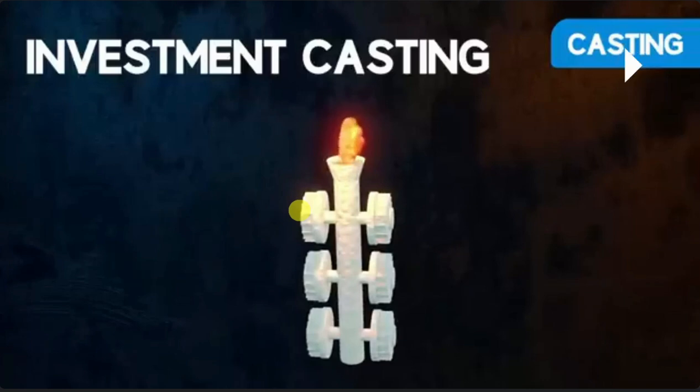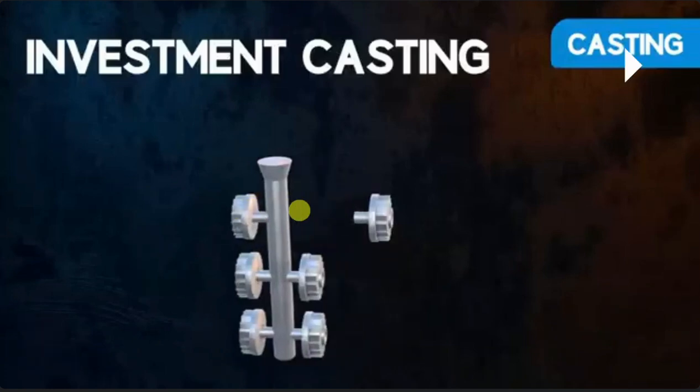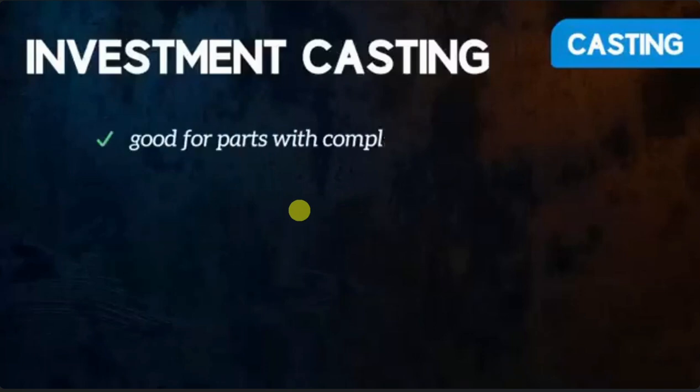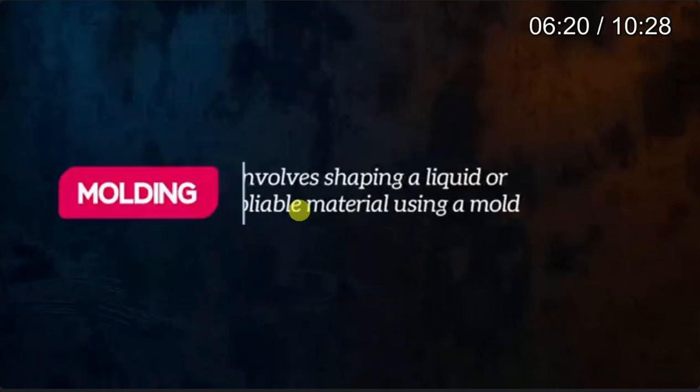Now they pour the molten metal, and once the casting has cooled, the mold is broken up. So once they pour the molten metal, they allow some time to solidify, then finally break that mold and get the product. This type of investment casting is used to manufacture gears, impellers of pumps, all those things. Investment casting is good for parts with complex geometry and can achieve tight tolerances, but it is an expensive and time-consuming process.